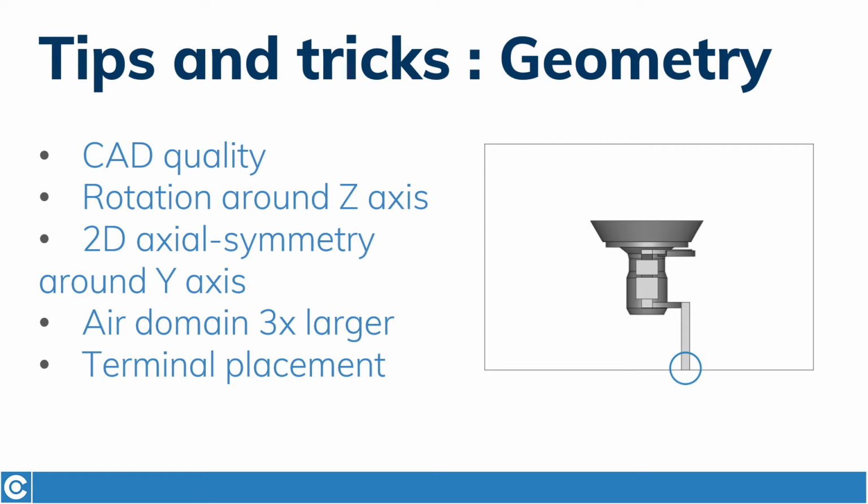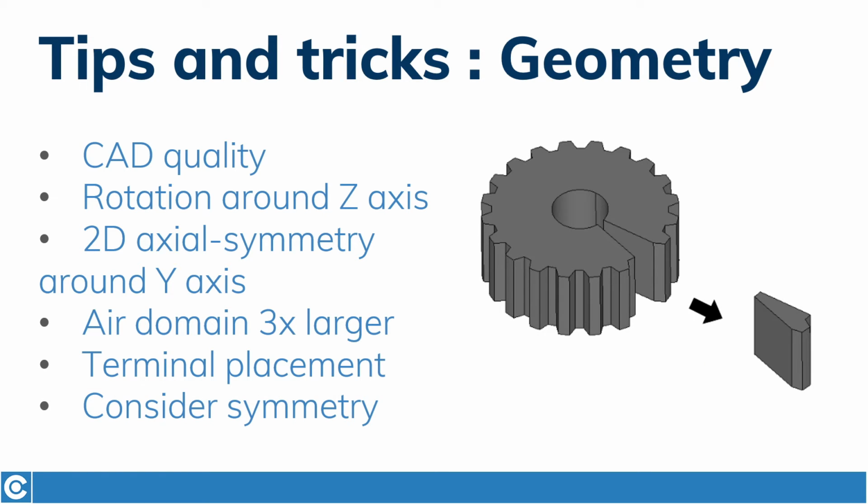If your geometry is at any level symmetrical, use that and simulate only half, quarter or a slice of the full geometry using symmetry boundary conditions available in CENOS.